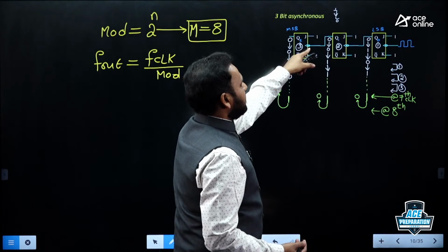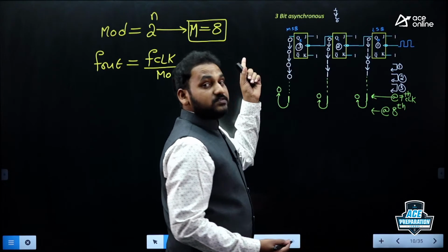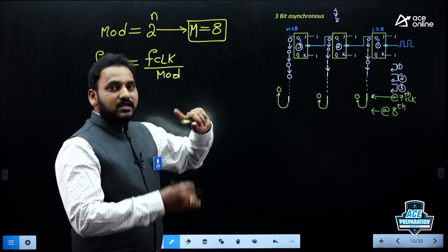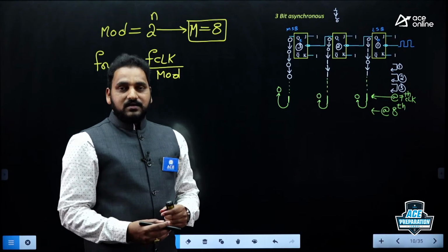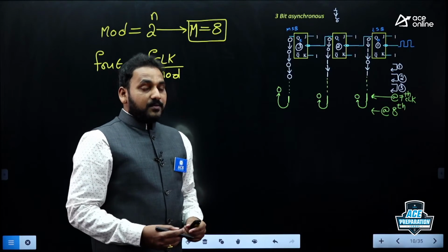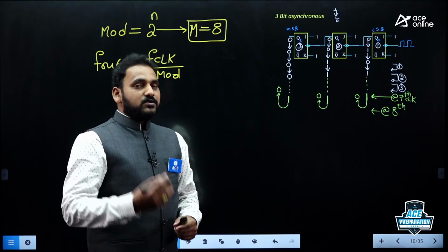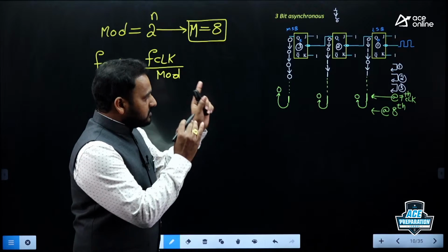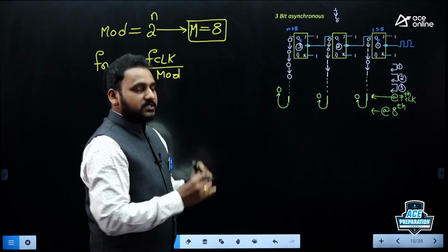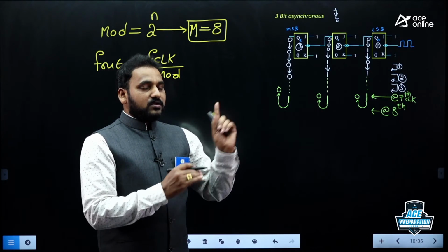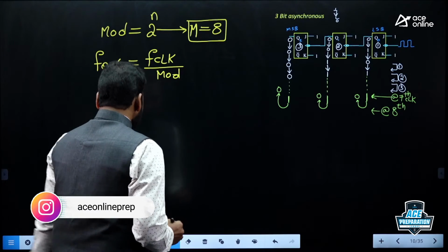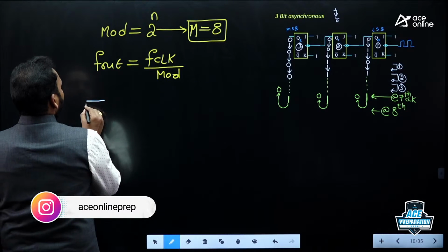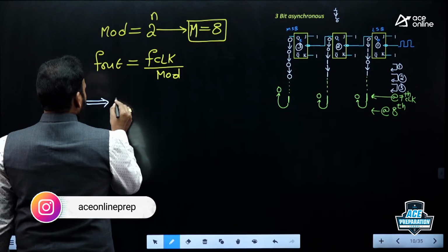If it is not a falling edge, then it becomes an up counter, but that story is different. There are two different ways to draw the circuit for up counter and down counter. But don't worry, I'm talking about a 3-bit, n-bit asynchronous up counter. You remember only these points, right? Next point, this is also called a ripple counter.